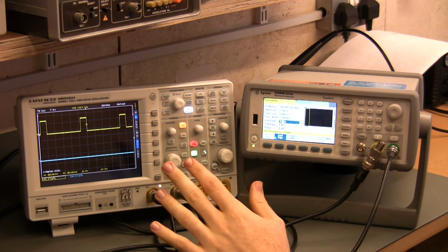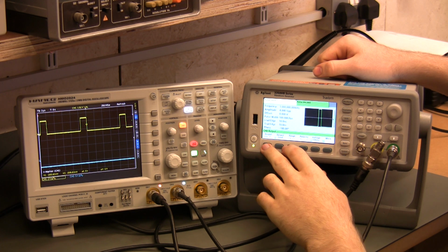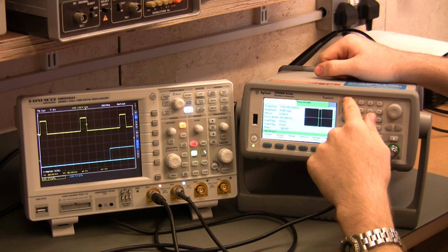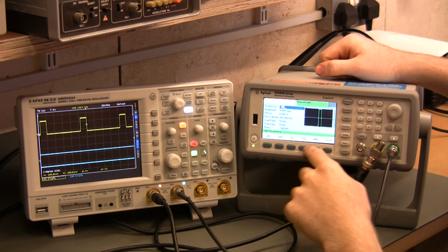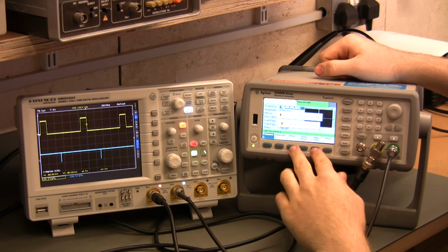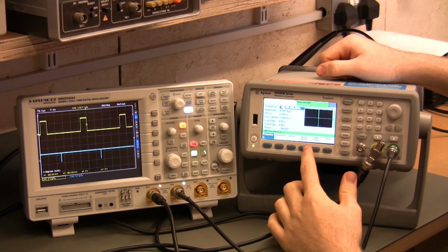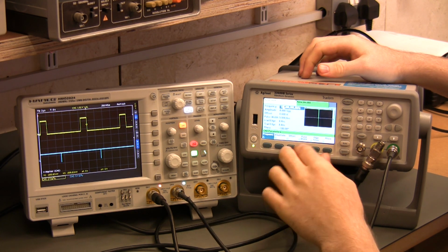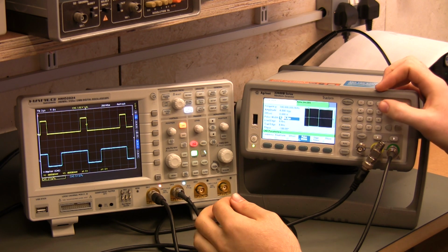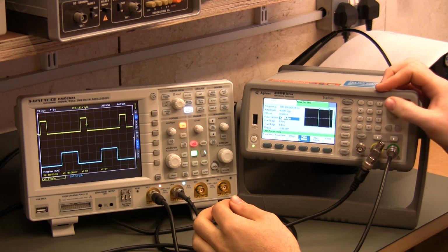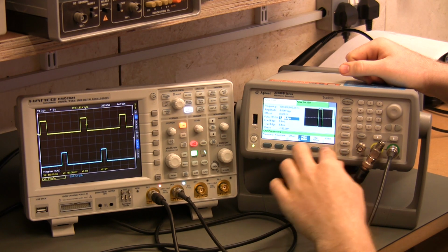Right, so let's have a play around, a bit more interesting functionality. Let's bring in channel 2. Channel 2 on, and let's go to, we're already in pulse here, frequency, let's do 100 kHz again. And it's actually quite nice on the UI. You notice if you set the parameters to something where it can't automatically do it, it does actually try and work with you, just try and bring it into something more sensible. And let's bring that right down. Right, so we've got 2 being generated here.